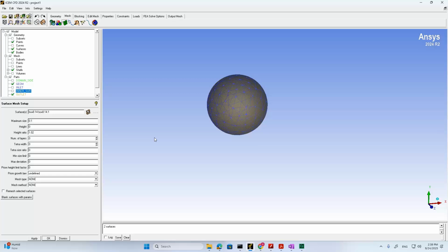This ratio is used to control how fast or how slowly the fine mesh is transitioned to more coarse mesh. So the smaller this number, this number has to be greater than 1. Otherwise there's no transition. If it is 1, then the mesh size is pretty much always the same size. It has to be greater than 1. So the finer mesh gradually grows in size. So the closer this number is to 1, the more smooth the transition is.